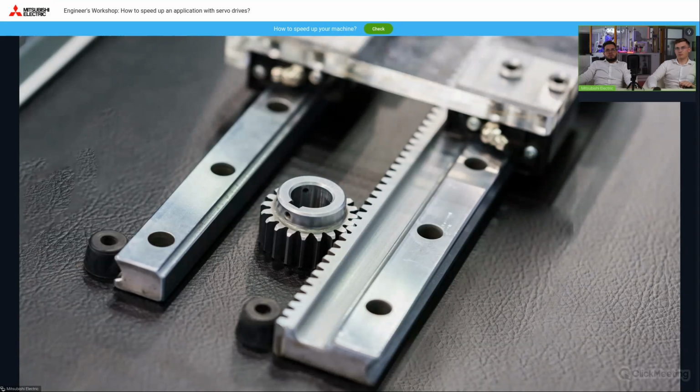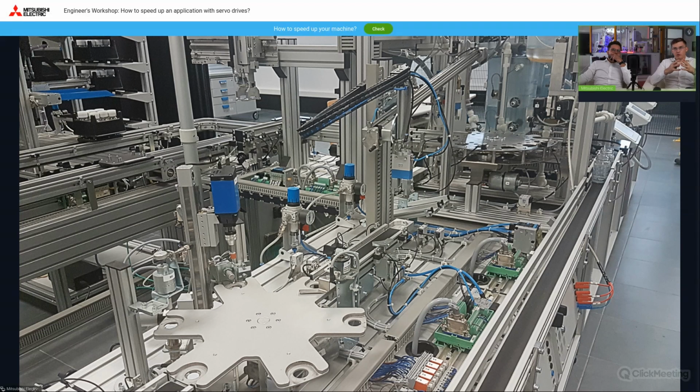But you probably wonder why we are proposing to replace pneumatics with other drives. So, because if you replace a two-position pneumatic actuator with a servo with appropriate mechanics, as Błażej mentioned, we can take advantage of more advanced control and accelerate the machine cycle not only by achieving higher maximum speed, but also thanks to the possibility of shaping trajectories, optimizing motion paths, and the option of simultaneous operation of the drives in the collision space.